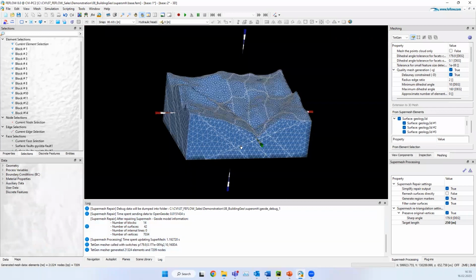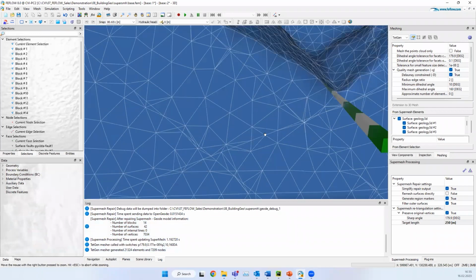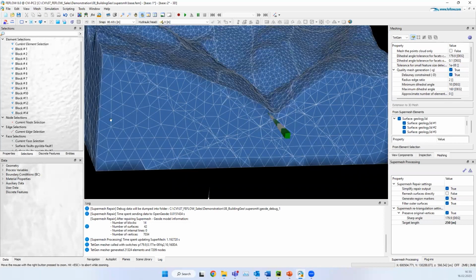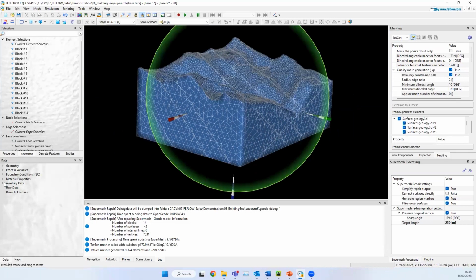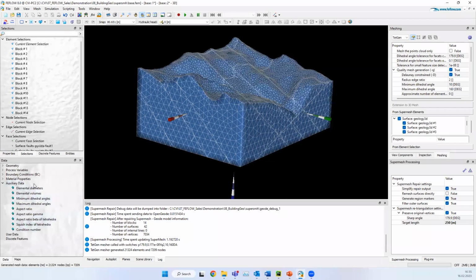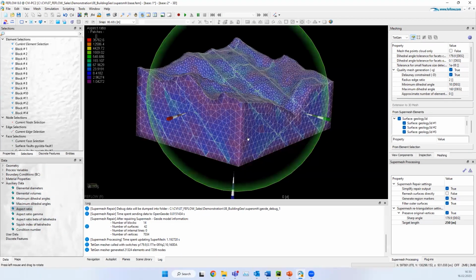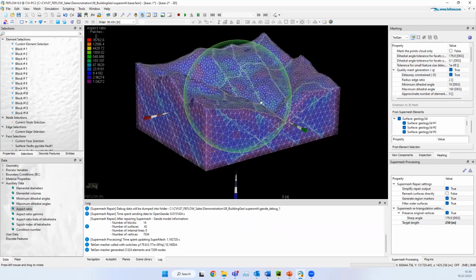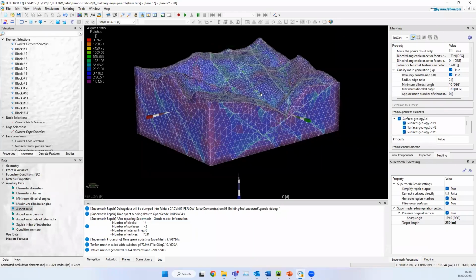The quality is good. If I zoom in here, because we didn't force any triangulation outside the repair, maybe we have some angles here that are not well connected. We can always look in auxiliary data, where you have a number of parameters to control, like the condition numbers. We can just randomly take the aspect ratio and see, yes, indeed, there are some tetrahedra with a very high value. So maybe it was not a good idea to just do a simple tetrahedral mesh after the remesh.